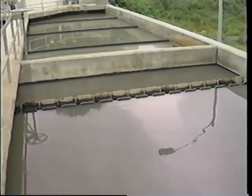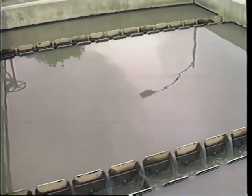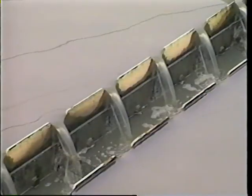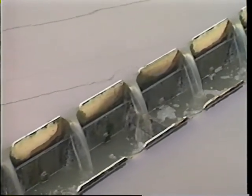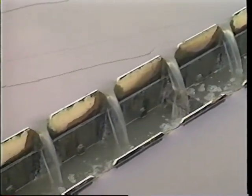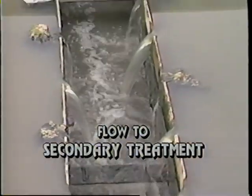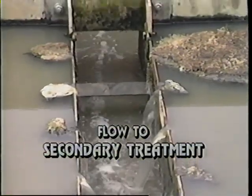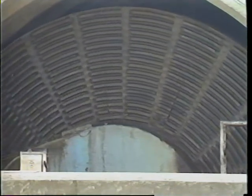After adequate detention time in the primary clarifier, the now clarified surface water exits by flowing over notched dams called weirs, which are used to control the flow velocity of the treated water. In many plants, wastewater that flows from the primary clarifier goes to a secondary treatment process. This is basically a biological treatment. With this process, the wastewater is exposed to bacteria, which eat the dissolved and non-settable pollutants remaining in the water.